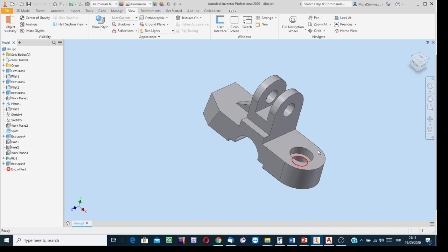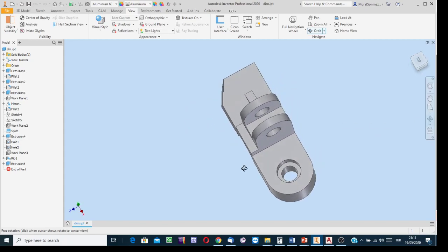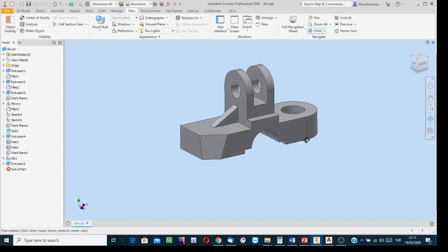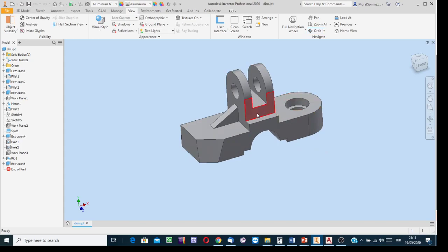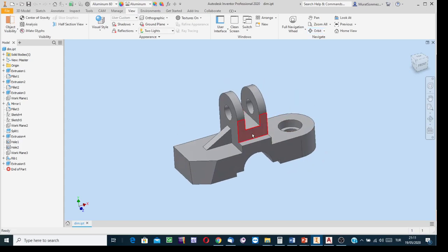And this is a counterbore hole, truly extending. At the top of the base, we have such a prismatic feature, a combined feature with such a step, and two semi-cylindrical extensions. Within the semi-cylindrical extensions, we have truly extending holes, this and that.